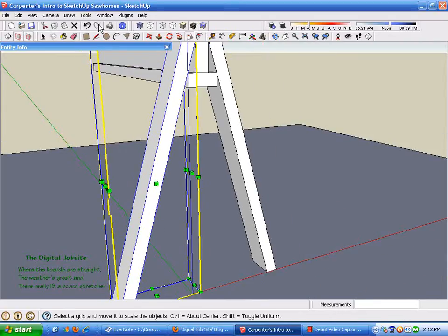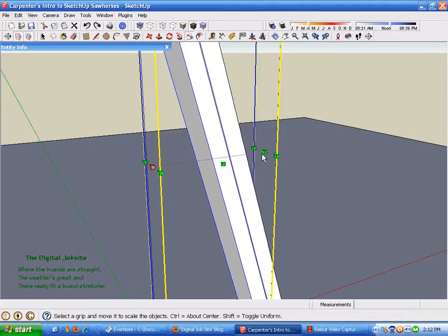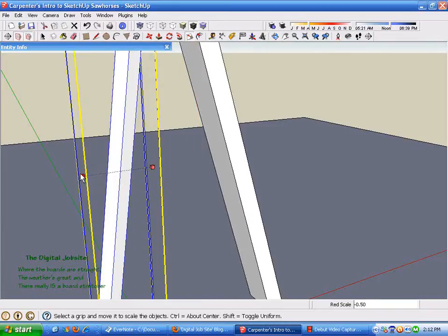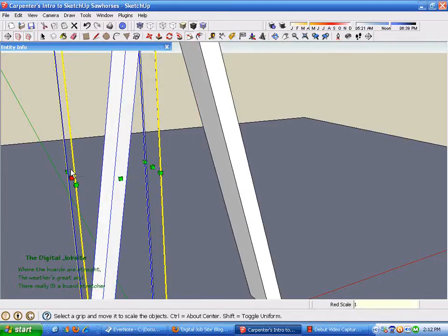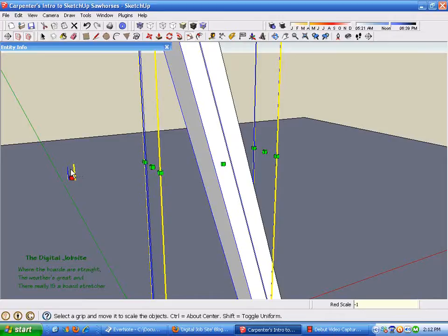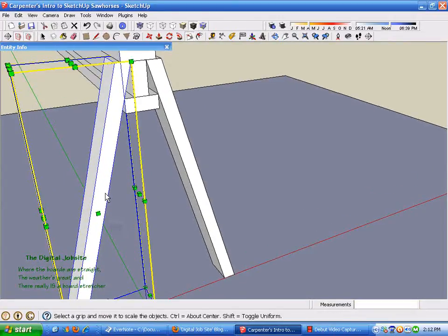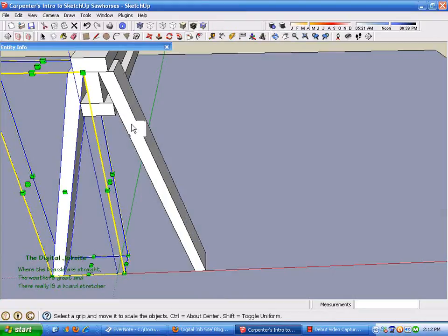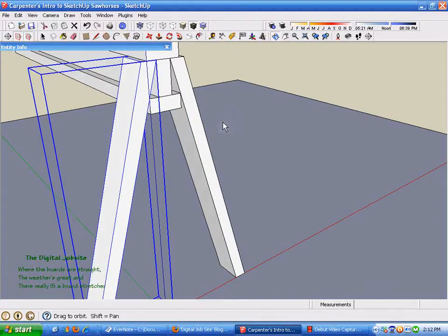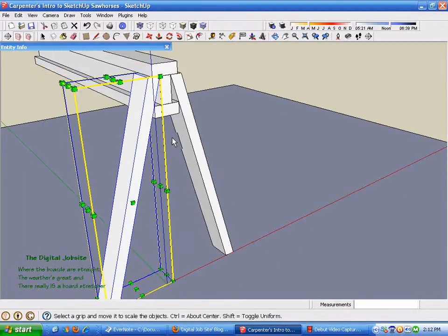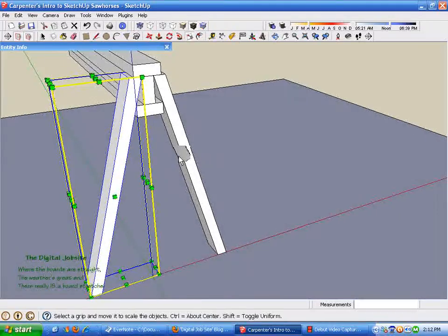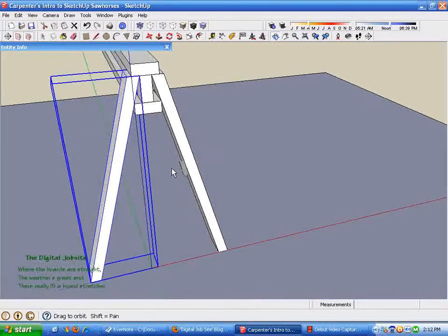If by taking the back arrow and we do this scale thing we can't get it to land on -1, just type -1, enter, and it'll make a mirror image of it. And so that will suffice. There are other interesting and useful features for that scale tool, but that's a good dramatization of it.